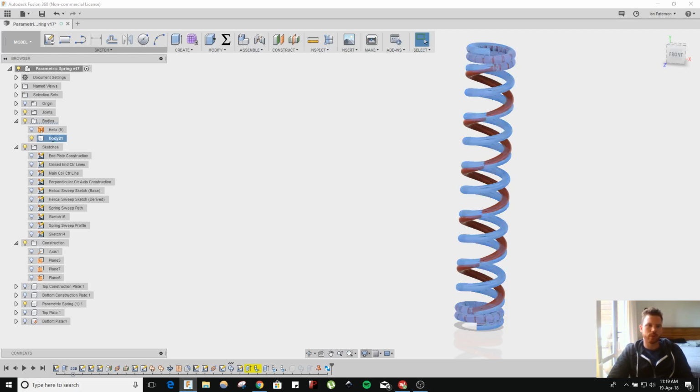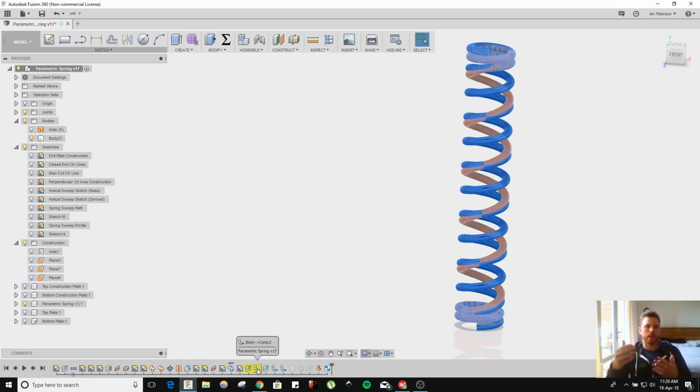So this body is created back here, and it renames the body something new because for some reason body 20 now existed at some point, but because I've regenerated the model, something is triggering it to make that body number index. And because this make-this-body-a-component feature points at that body name, it falls over because it doesn't have body 20 anymore.